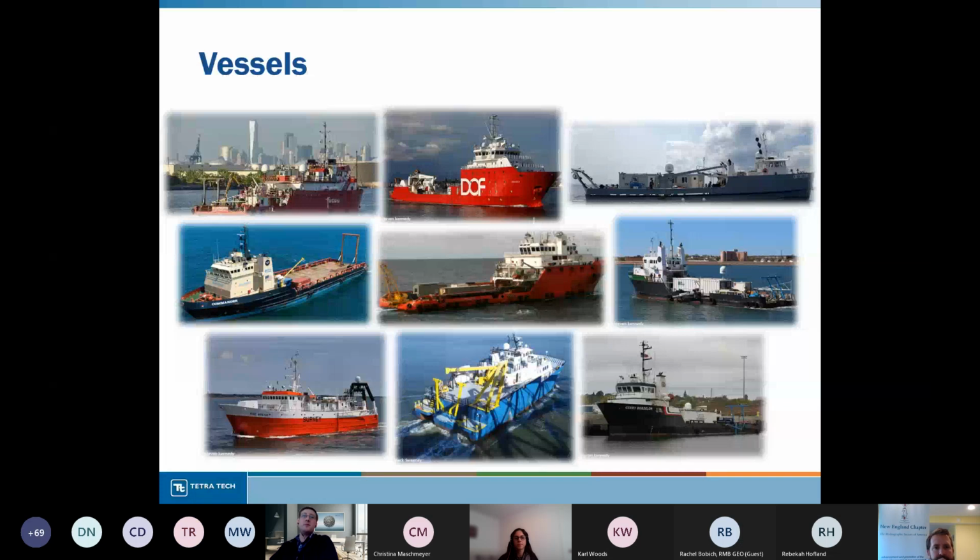They take a fairly common shape of a wheelhouse, a big flat deck to put lots of equipment on. Sizes usually about 150 to 300 feet, and they're equipped with everything you'd expect for quite wide-ranging geophysical survey: winches, A-frames, side poles for the equipment that needs to be in the water all the time. And because of where the survey areas are, we're typically looking at ideally week-long durations, quite significant crews out there.